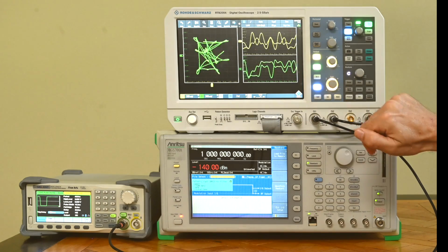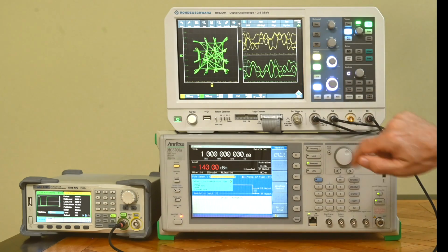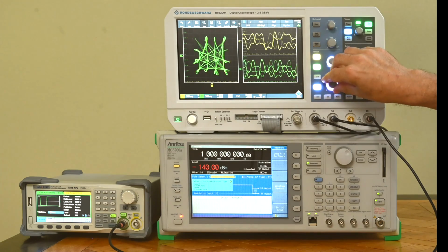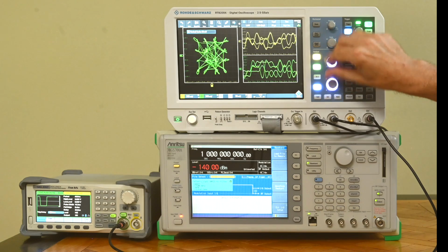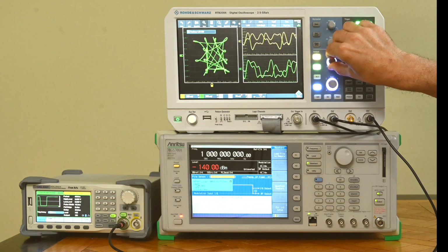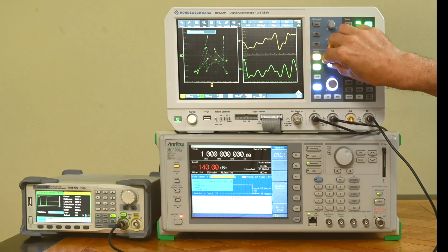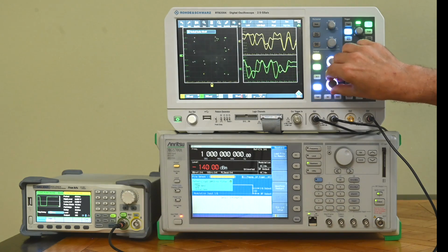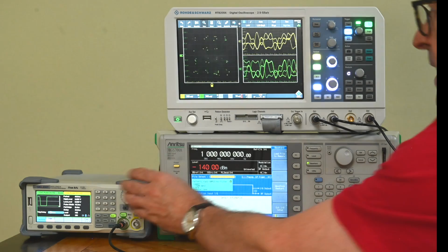And I'm going to use channel 4 for blanking. I have to put it to quite an extreme position. It has to go into overload a bit, I'm afraid, but I've been experimenting a little bit with it, and that's actually the way to go. If I do this and I take my vertical position to a low value, yeah, there we basically, it's a little bit of experimenting around. There we actually see it coming.